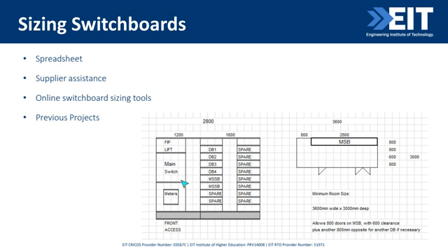This sketch here is estimating about 2.8 meters for the main switchboard. And from there, the room has been sized. So you've got double doors to get your board in and out. You've got enough clearance in front of your switchboard for egress, and your wall is long enough to house that board. So this is a very rough check to size a main switchboard.